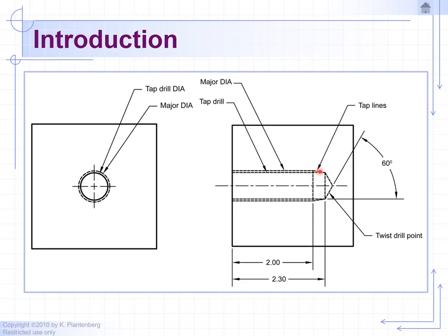And then you go beyond, and this is where it starts tapering. Then we have this V shape due to the drill. So first you'll drill a small diameter hole, and then you come in and tap it. This represents the end of the drill, which has a conic shape. It's just easier to scoop material by having a conic end on the drill.